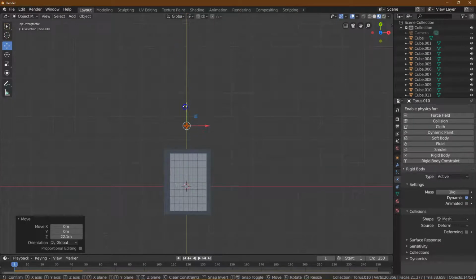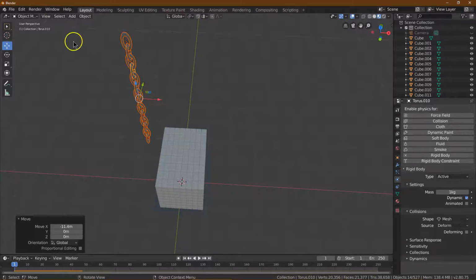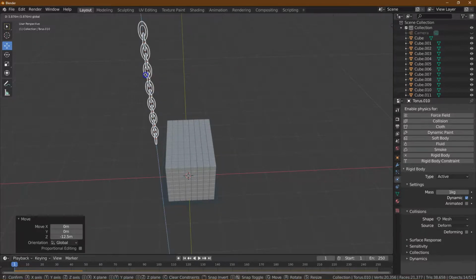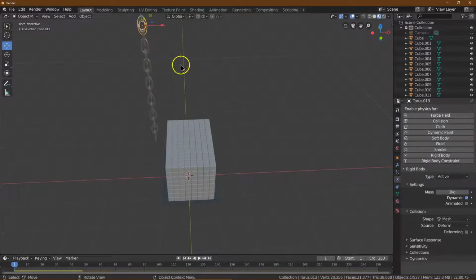Grab that. Let me get from the z-axis here. And since it is going to be going back and forth, we are going to want to have the chain facing in the right direction for that. Okay, that looks great. I'm going to pull it up a bit. And so what I'm going to want to do now is I need to make sure that this part doesn't move, right? It's going to hold the chain up here and our balls. So to do that, all we would need is to uncheck dynamic over here. If we uncheck dynamic, that chain will stick right where it's placed.